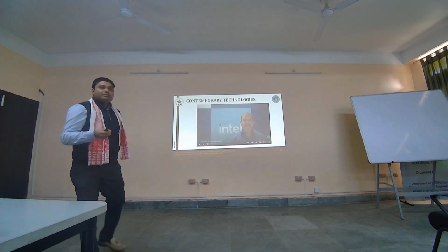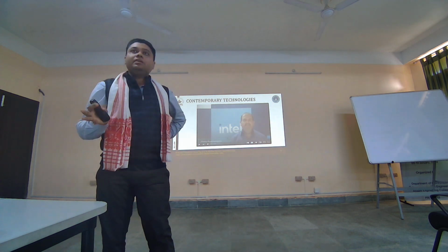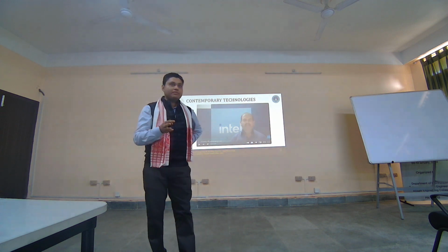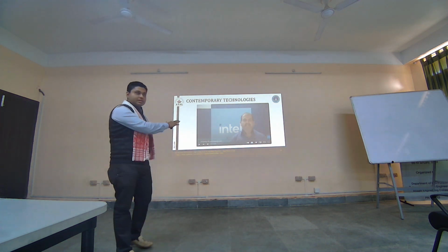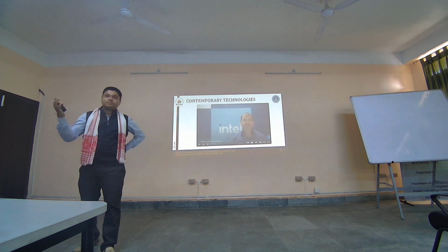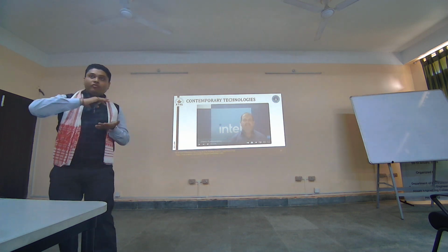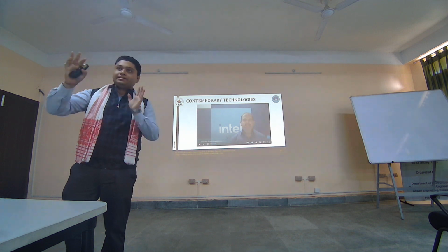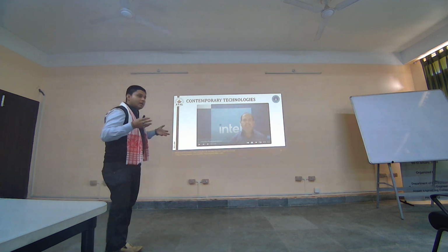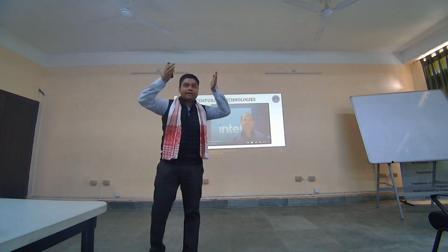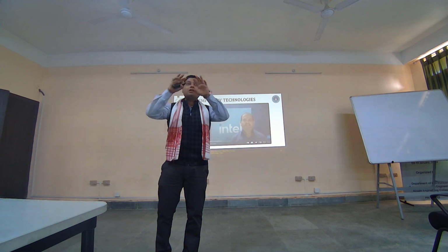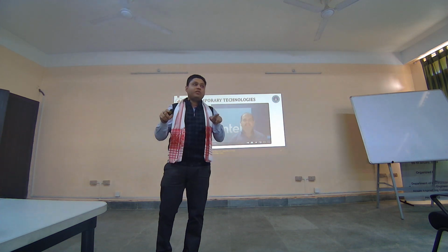Okay, so recently, I think in 2021, Intel and Samsung both went for gate-all-around structures of devices, which is what this person is going to speak about. When we talk about MOSFETs, these are planar structures, right? The gate is just over the channel, and it stays there. But in the case of FinFETs, you convert it into a 3D fin kind of structure where you have the gate wrapped around that entire structure. So you have control from three sides of your channel.